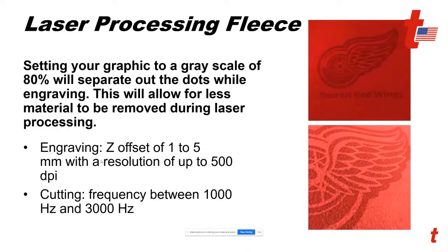This material works very well with the laser system. It doesn't require a lot of laser power, depending on the pile, and the pile is basically how thick the material is and how fluffy it is. The thicker it is, the more power you're going to need, and possibly a little bit slower. I always start my fabric at 100% speed when engraving, and I start my laser power pretty low, and then I'll bump it up. You can adjust your laser setting on the fly, or pause it, make an adjustment, and resume until you dial in that setting. If you're deciding to do something like any of these fabrics, make a setting. Create a setting in your database for fleece, and then you have one from then on.